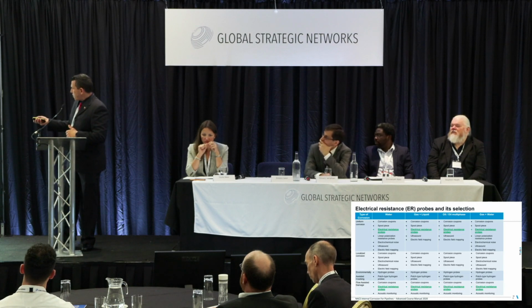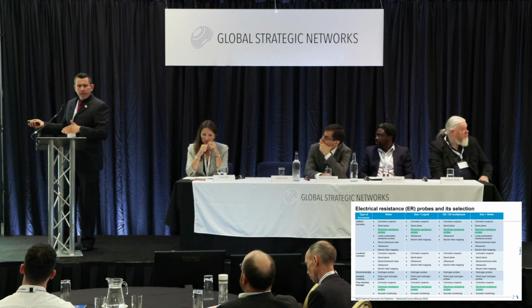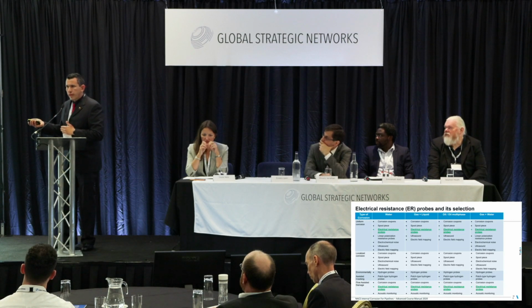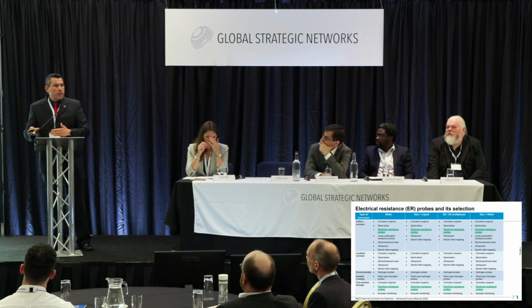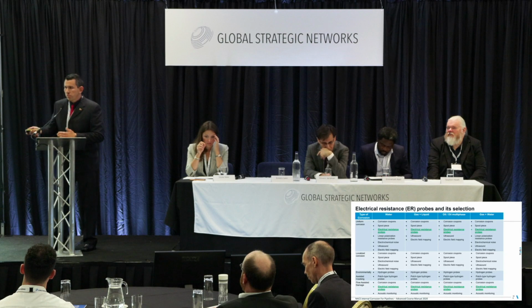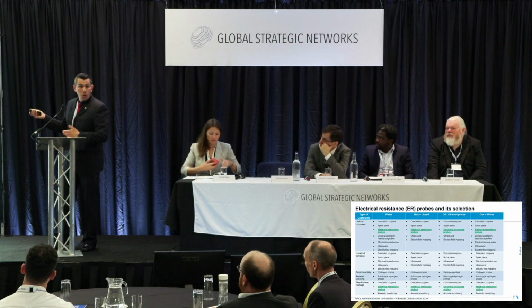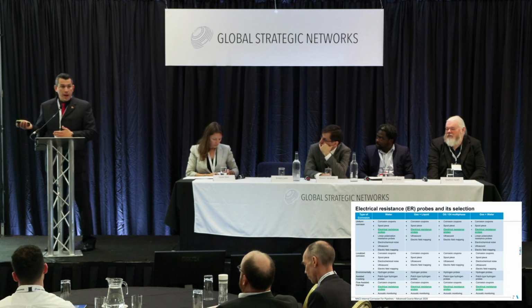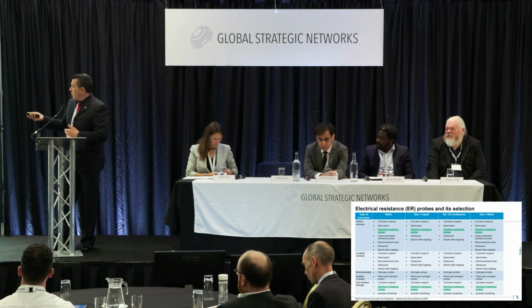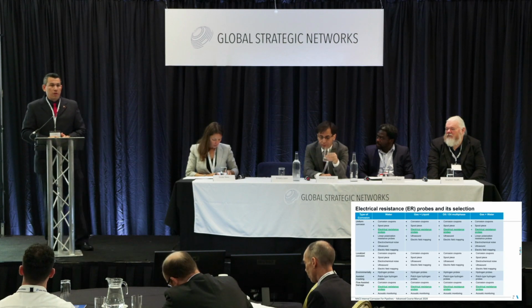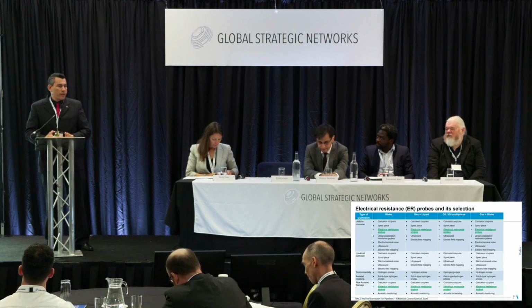In this table, I only want to highlight, as you can see already in green, that electrical resistance probes can help you in most of the media that we have in oil and gas production. Those are water, gas and liquid, oil and oil multiphase, and gas plus water. But they can't be useful to assess all the degradation mechanisms.